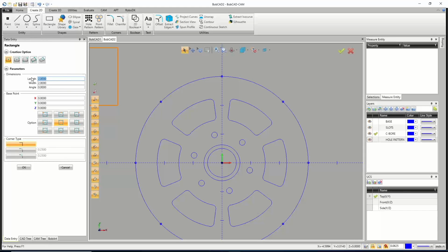So it's going to be a 2-inch wide slot or groove, whatever you want to call it. And then we're going to go with a width of 1, there we go, 1/2 inch deep. So there we have it. Now what I want to do is make sure we have our radiuses added onto this right at the start. So I'm just going to turn on these 1/4 inch fillets. All right. And that's the default.